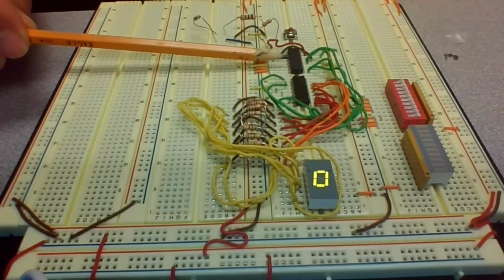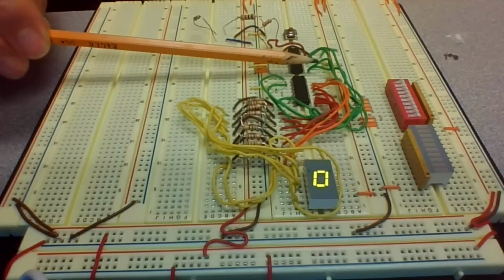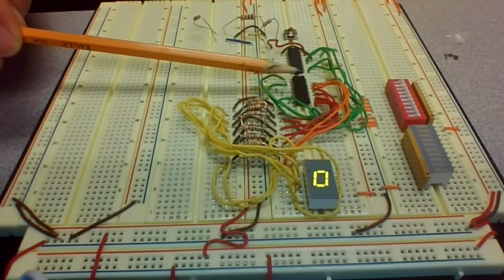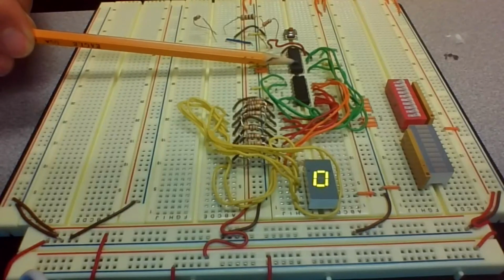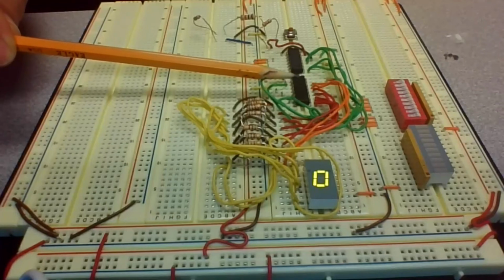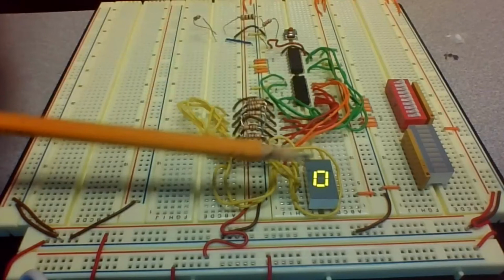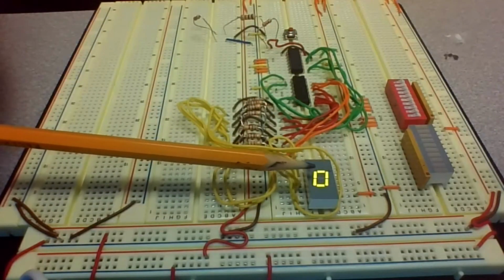Here we use the 74LS90, which is the BCD counter, and we connect the output of the BCD counter to a code converter. This is the 74LS47, which is the BCD to 7 segment code converter. So that means here we count from 0 to 9 in BCD. Then we have this code converter, which converts the BCD to 7 segment, and we are able to see the 7 segment code here on the 7 segment display.